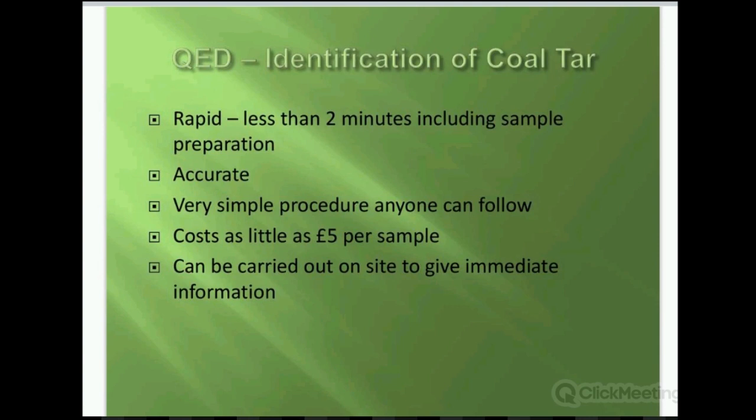So when we start looking at the new rules on incorrectly classifying your waste, and the new rules with RPS 211, I do feel sorry for anyone who's digging holes in the road, because as soon as you've dug through the road surface, you effectively have to classify that material as hazardous unless you can prove otherwise, which means you need to take it to a site that is licensed to take hazardous material.